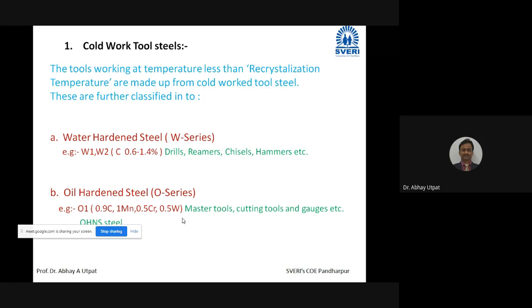Ferrite is soft phase and cementite is hard phase. And in turn, as pearlite is mixture of ferrite and cementite, pearlite is harder by virtue of cementite. If you compare ferrite and pearlite, pearlite is harder because pearlite contains cementite. And if you compare pearlite with pure cementite, cementite is harder than pearlite because pearlite consists of soft phase alpha along with Fe3C. This is simple logic. Now, more than pearlite, what is harder? Martensite and bainite.